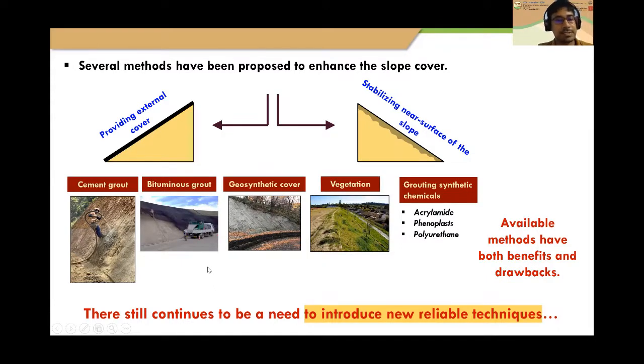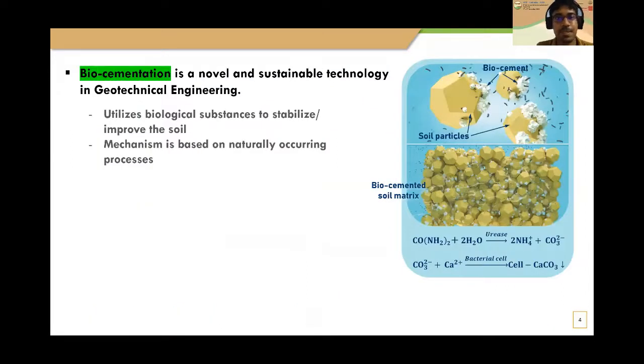Methods like cement grouting, bituminous grouting, and geosynthetic cover actually have a number of environmental issues. In particular, synthetic chemical grouts are known to be hazardous and toxic materials to the geo-environment. So it's very clear that there continues to be a need to introduce new and reliable techniques to the field of geotechnical engineering. Biocementation is a novel and emerging sustainable technology in the field of geotechnical